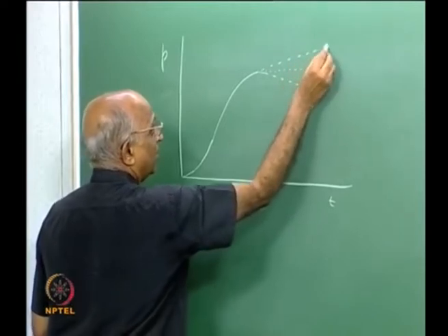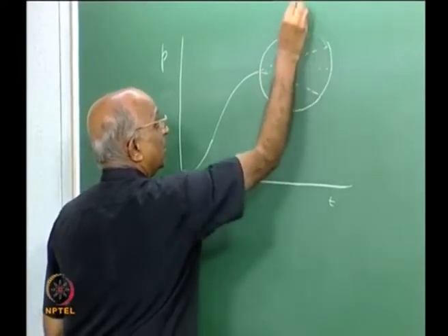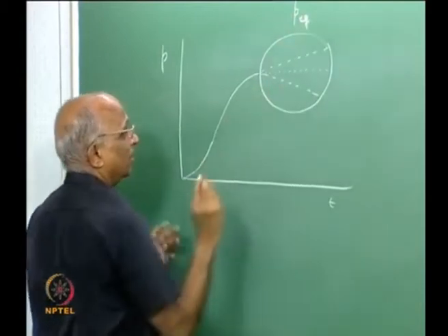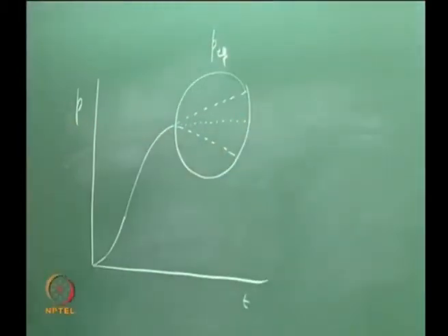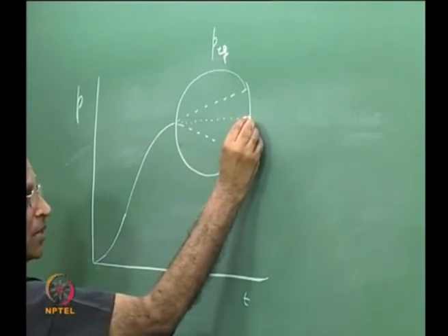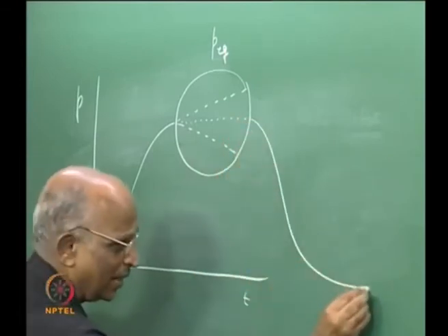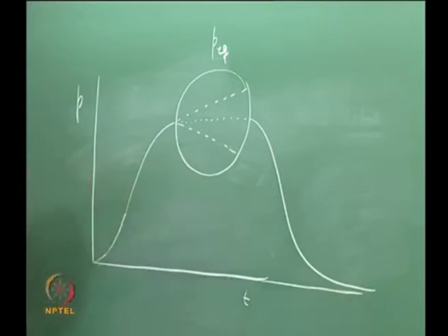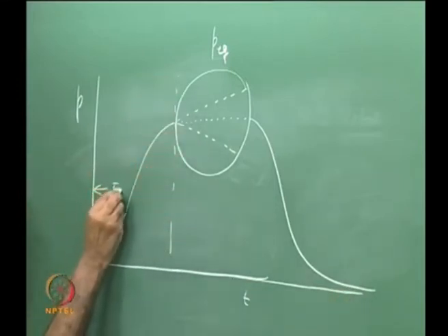Mind you, this particular zone is equilibrium pressure, right? That means a steady state pressure. At the end of this, what happens is, well, all the propellant gets consumed, it goes like this and comes back over here. This is the transient for ignition, ignition transient.